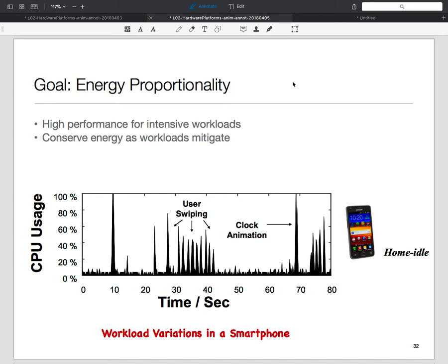Okay, let's restart. There was some question about interrupts and how we wake up out of this. The source of the interrupt could be outside, like pressing a key or some sensor which is monitoring, or it could be just a timer. Before you go to sleep, you set a timer saying wake me up in, say, 5 seconds, and then the timer does it. Usually these chips have a timer or something like a timer which is designed for such wake up.